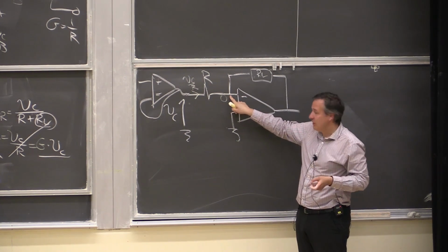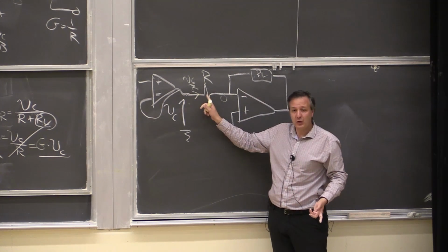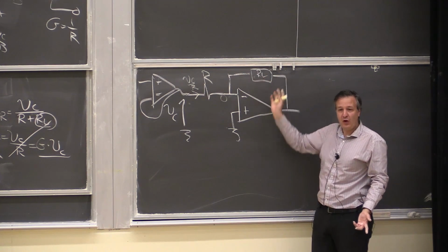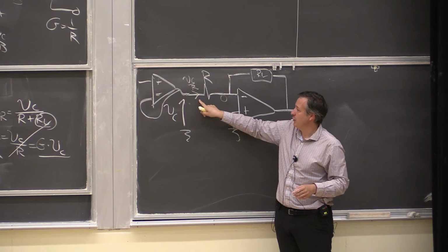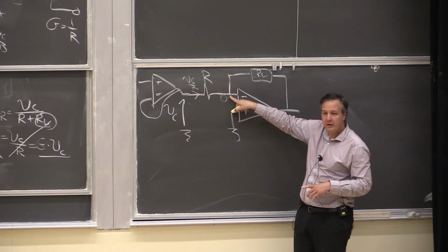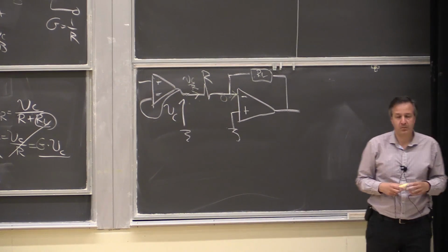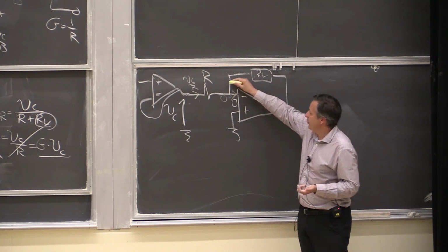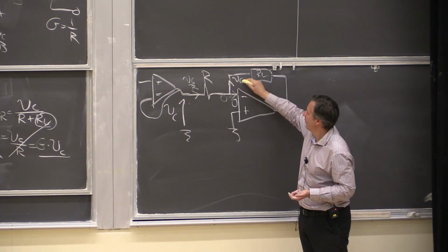The fact that this voltage is 0 is really sweet, because now the current here is only determined by VC minus this 0. So whatever is happening on the load does not influence it at all. And so we get just clean VC over R. Then, as that current goes this way, it hits this node. What is the current going into the op-amp? 0. That's the first golden rule. And so that makes all this current VC over R flow this way.